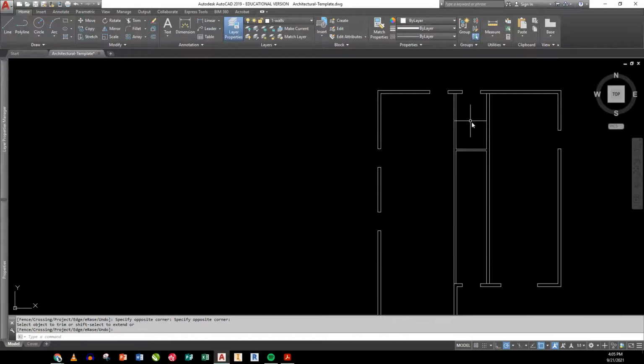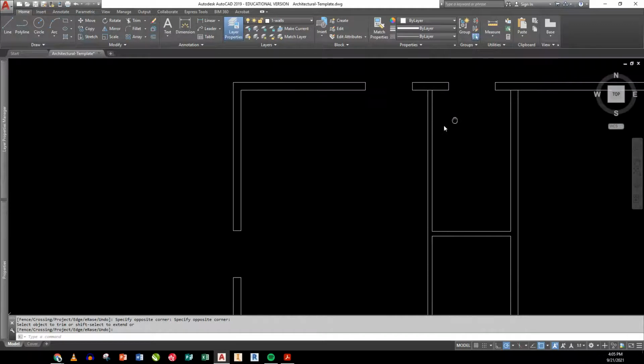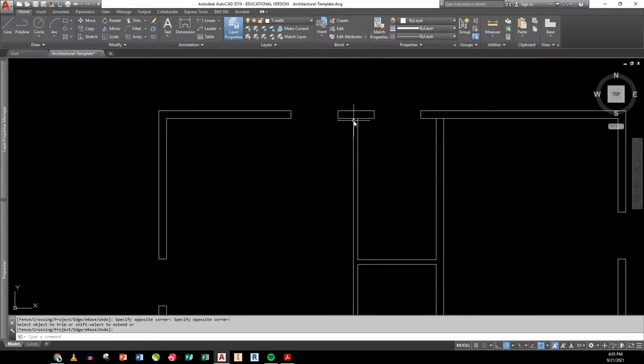Okay. In my bathroom, I would have drawn this. I would have actually taken that 2'10" side and robbed basically 4 inches off it, which would make it a 2'6" centered bathtub. Okay. But we've not taken that into account here. So they've drawn their nominal walls at 5.5. So honestly, let's look at this distance from this corner here to this corner here. I've got 5 feet and half inch.